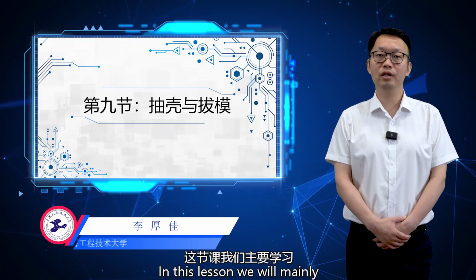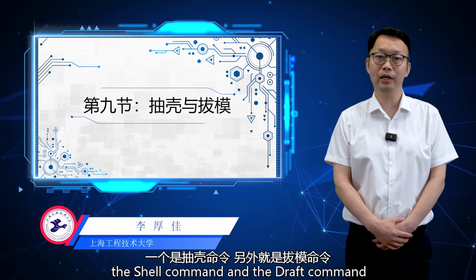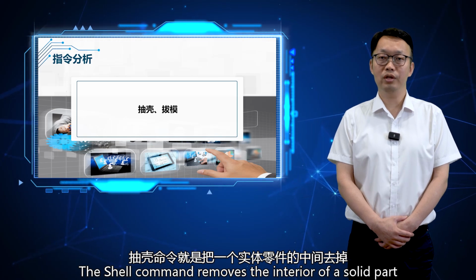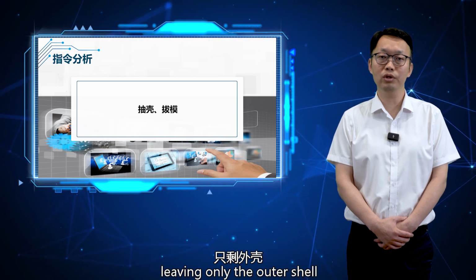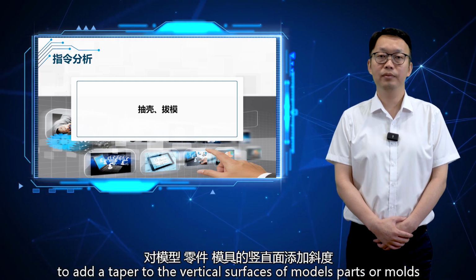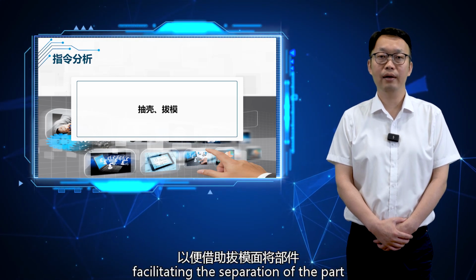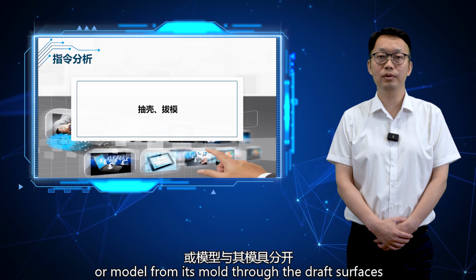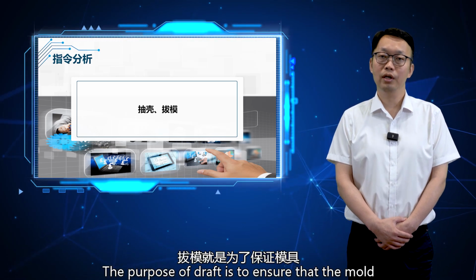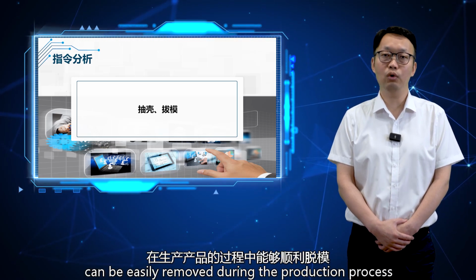Hello everyone. In this lesson, we will mainly study two commands, the shell command and the draft command. The shell command removes the interior of a solid part, leaving only the outer shell. Draft is usually used to add a taper to the vertical surfaces of models, parts, or molds, facilitating the separation of the part or model from its mold through the draft surfaces. The purpose of draft is to ensure that the mold can be easily removed during the production process.